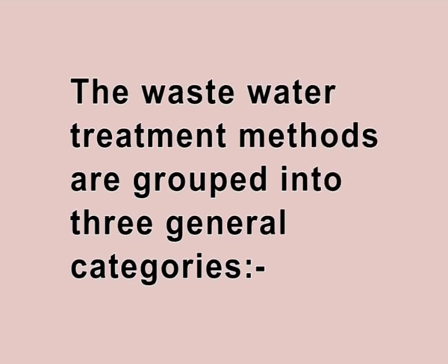It is necessary to remove plant nutrients, nitrogen and phosphorus, and also disinfect with chlorine to destroy most pathogens and to help prevent the transmission of communicable disease from wastewater. Considering this in general, the wastewater treatment methods are grouped into three general categories.